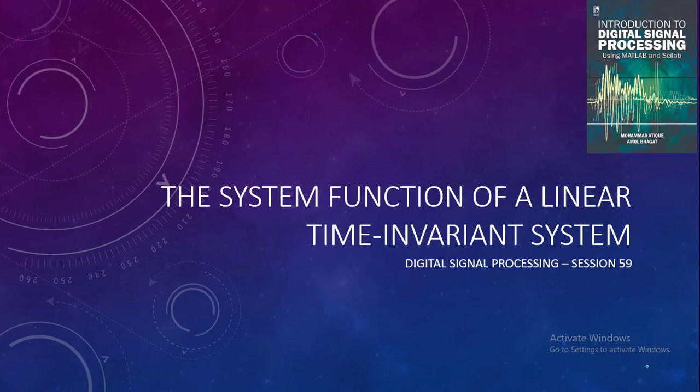Right? We can even identify the bounded and unbounded nature of the causal signal. If poles are outside the unit circle, then the signal becomes unbounded. Such signals should be avoided, right? And if causal signals have poles inside the unit circle or on it, the signal becomes bounded, right?